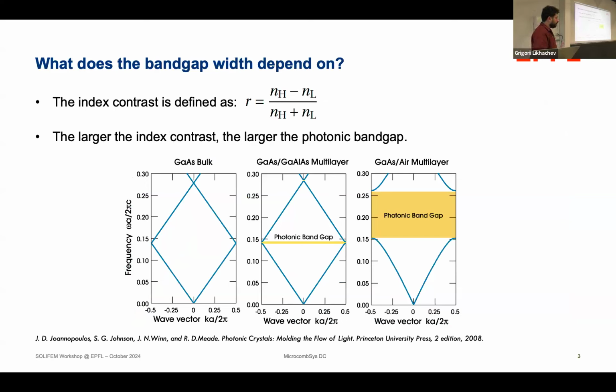And that's what we call a bandgap. So let's look at it this way. If you don't have a photonic crystal, so it's just a bulk material like gallium arsenide, or if you have a waveguide, what you will have in frequency is a band structure, exactly like the ones you have for electrons in a periodic lattice. It's the same concept of a periodic lattice, which for photons is the refractive index, and for electrons is potential.